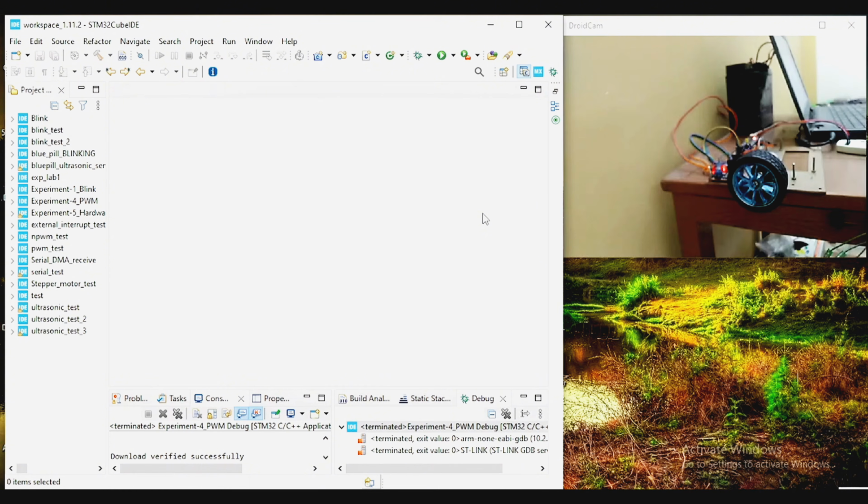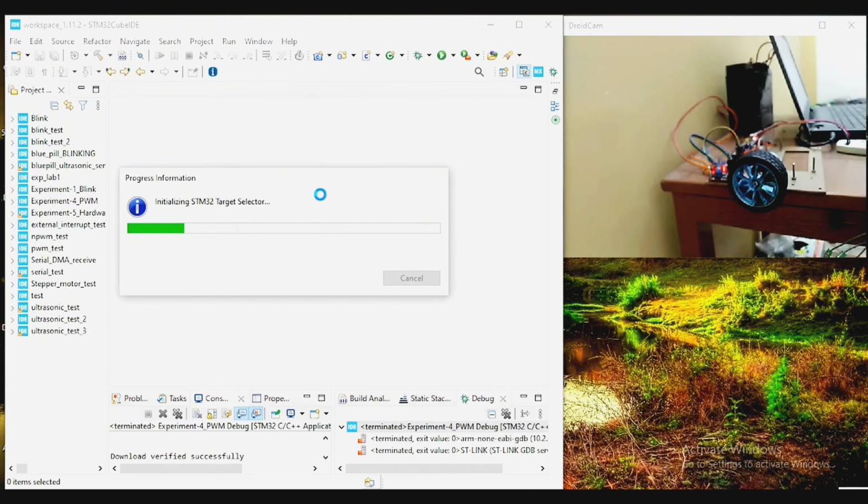Pulse width modulation generation using STM32, with an emphasis on how the circuit is connected, especially when the PWM output is used to control a DC motor or a servo motor via drivers like L298N or directly via transistor.